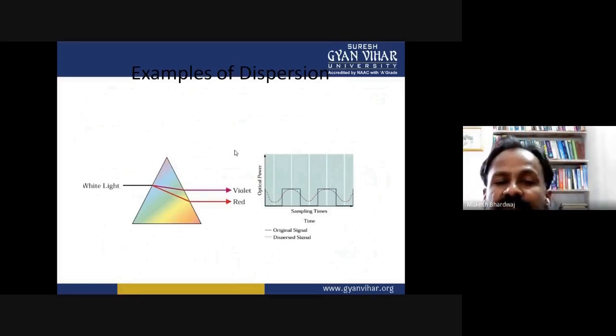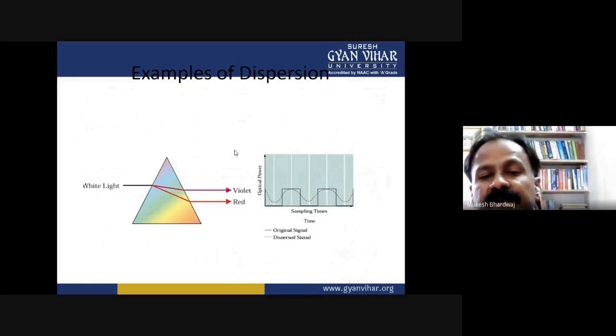The first stage produces a preform cylinder of silica composition 10 to 20 centimeters in diameter, about 50 to 100 centimeters long. This preform consists of a core surrounded by clad with a desired refractive index profile, a given attenuation, and other characteristics. In other words, this is the desired optical fiber but on a much larger scale.